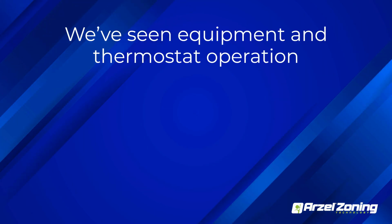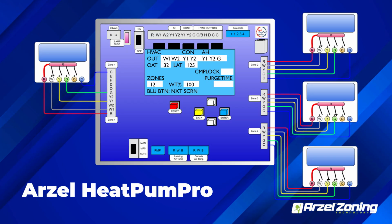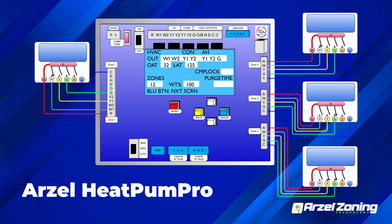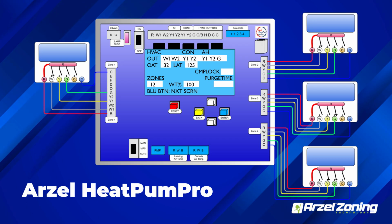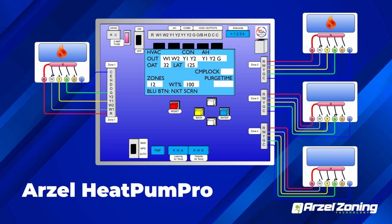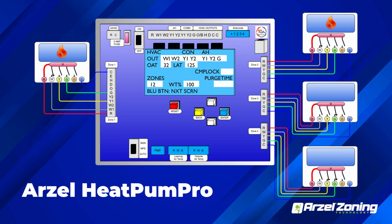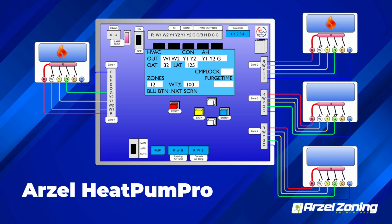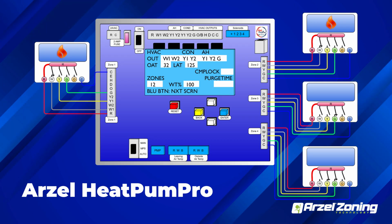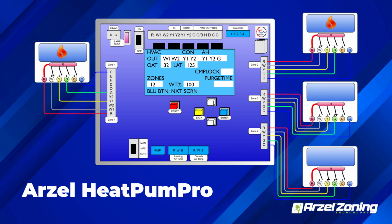Now that we've seen the equipment, now that we've seen how the thermostats operate, we need to add zoning to it. The zoning system takes multiple thermostats, applies a set of rules, and gives you your outputs. When we have the Arzel HeatPumPro, all it needs is a W input, and it'll provide you with up to 4 stages of heat, 2 stages of cooling on the outputs based on your configuration. So if you have an all-electric system, a heat pump with 2-stage electric backup heat, the HeatPumPro will provide you with 4 stages of heat, starting with first and second stage condenser, moving to first and second stage of backup heat if necessary, based on your leaving air temperature.